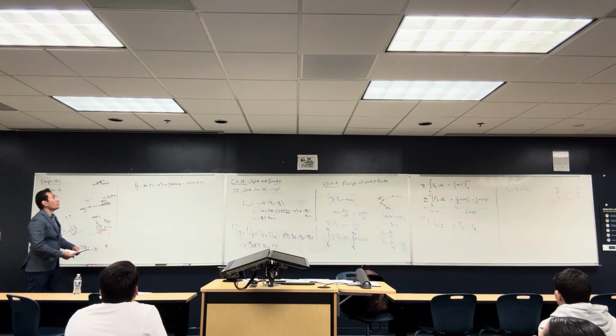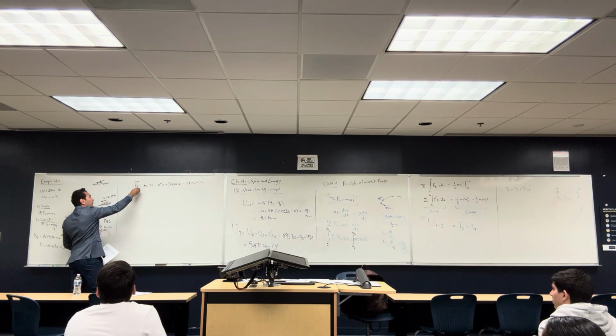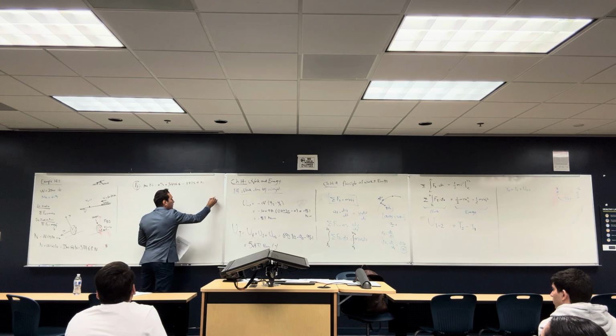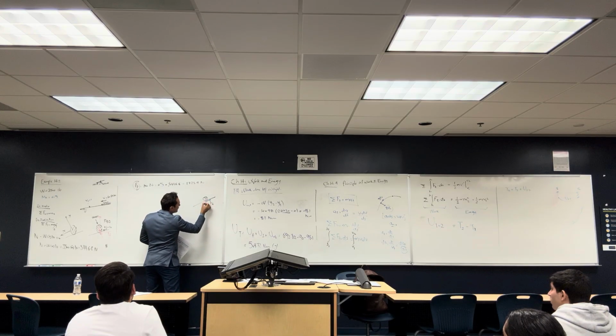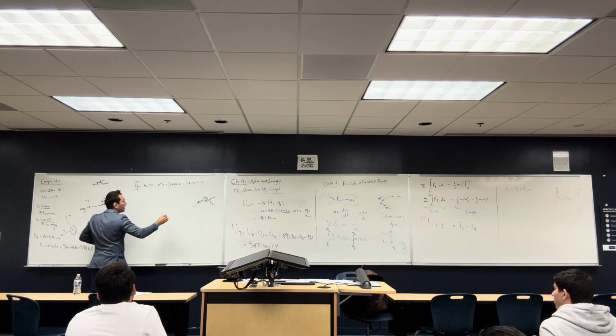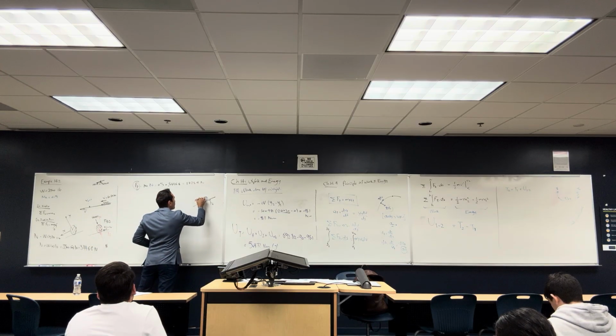And once I solve it, I'm going to find the value of the normal force to get F friction. Okay, so right now I have F of friction, and my body is something like this, and F of friction is that way, and the weight component is going that way, this weight component, the W sine 10.